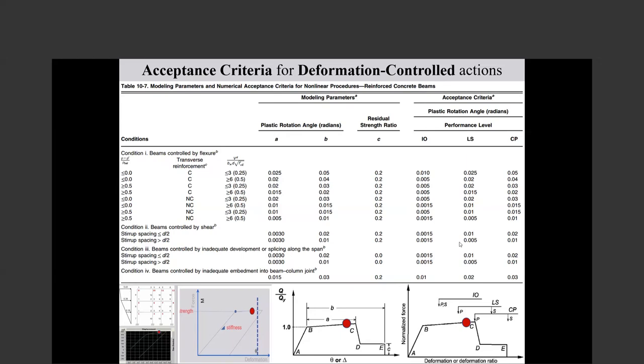But for the smaller ones, there are a couple of modes of failure, mainly in shear. And for them, both the vertical and horizontal reinforcements to get the shear are very important. Now that you mentioned that, I should write somewhere, there are a couple of very good references on shear walls.